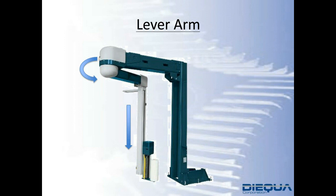What happens here is you have a cantilever load illustrated by the vertical down arrow. This arrow has a force that pulls down on the horizontal lever, inducing a bending moment, or if you would, a tilting torque on the face of the reducer. And to illustrate where the reducer would be, you'd focus on the round face of the unit, as illustrated now.